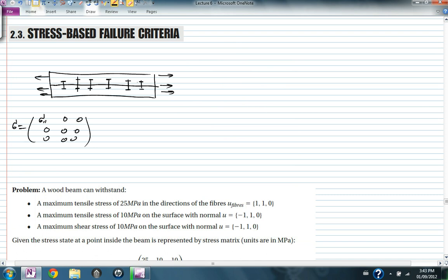Now those shear studs will never fail, because the stress on this plane is always 0. The sigma 12 is always 0. So the shear of these studs is not expected, and so it's really dependent on the orientation. Even if I increase sigma 11 as much as I want, and if I'm just worried about the failure of this shear plane, this will not happen.